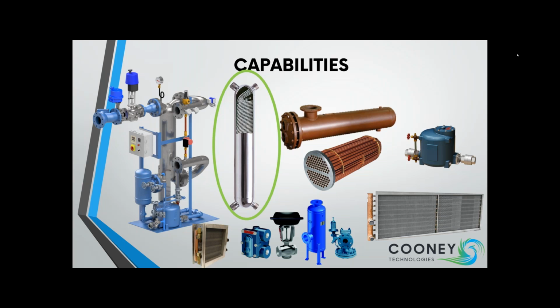One of the recently supplied Ivy League heat exchangers that we delivered, we could give them 820 gallons per minute of 180 degree hot water, and subcool their condensate, so their condensate's coming out at 110 degrees.